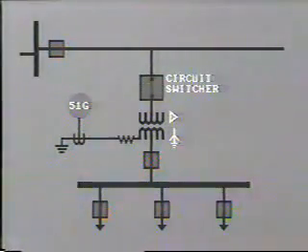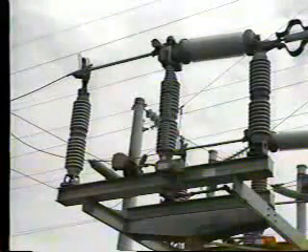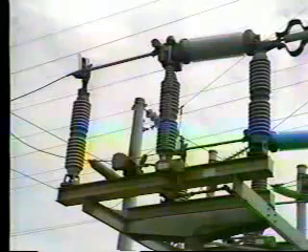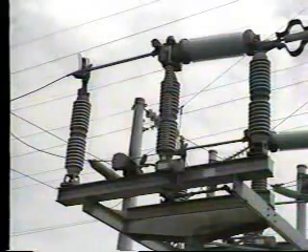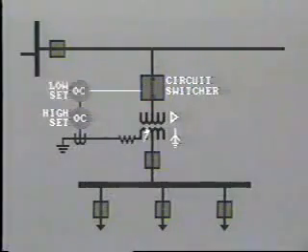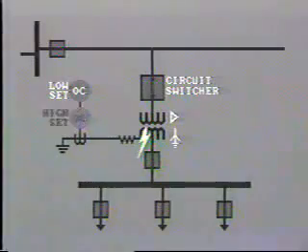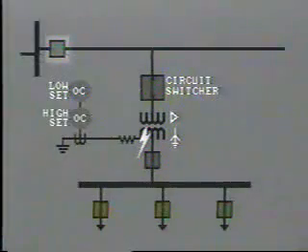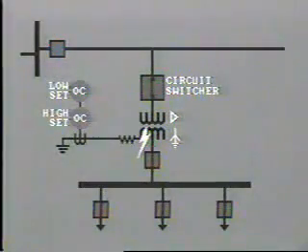Generally speaking, the ground switch arrangement is not often used on new installations. Instead, a circuit switcher may be installed on the transformer primary instead of a high-voltage fuse. This is far less expensive than a circuit breaker, but in return it provides very limited fault interrupting capability. If the fault current is low, this switcher will be quite capable of interrupting the circuit. If the fault current is above the circuit switcher's interrupting capability, this high-set overcurrent relay picks up instantaneously. This blocks the circuit switcher's control unit from operating and thus the circuit switcher from tripping. Then the remote protection at the substation will register a fault on the feeder and trip the circuit breaker.